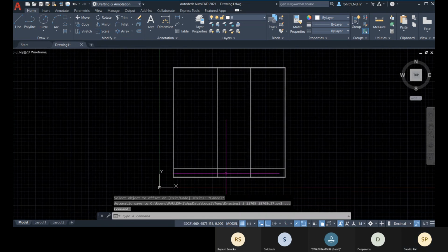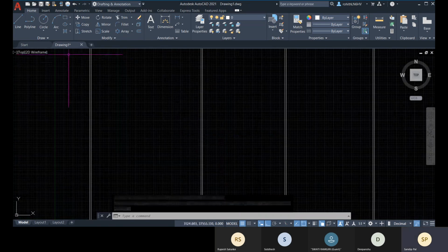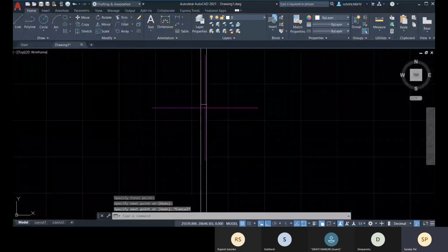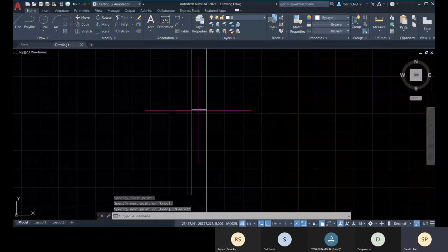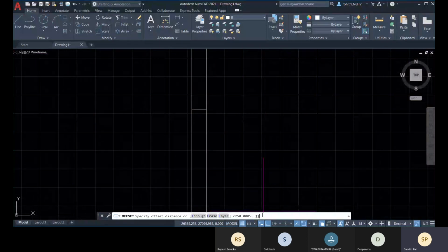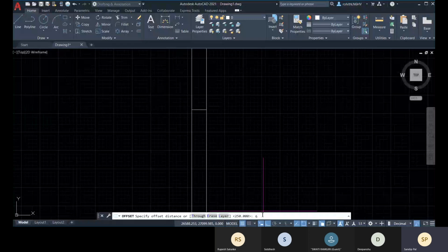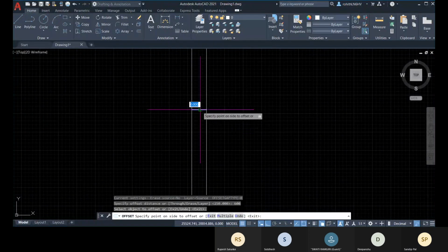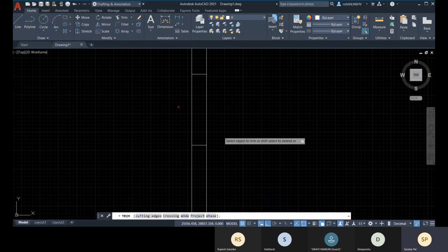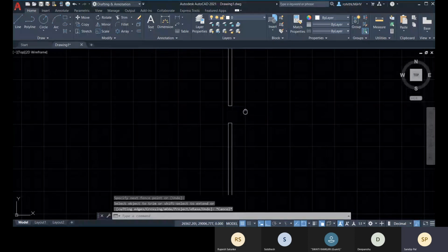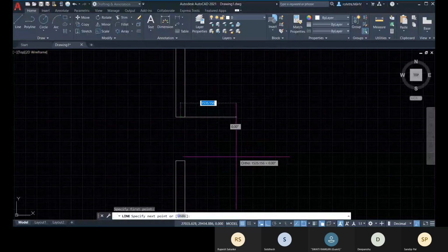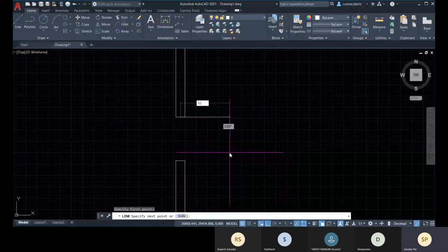After that, you can place a line over there, like this, at the middle. And as per the door length, you can create an opening. So what is the door length? Suppose the door length is 1200. So from the middle, it will be 600 mm. Then the total length is 1200, and you trim it, and your door opening is created. And then you can create a door symbol there. The length will be 1200, enter.